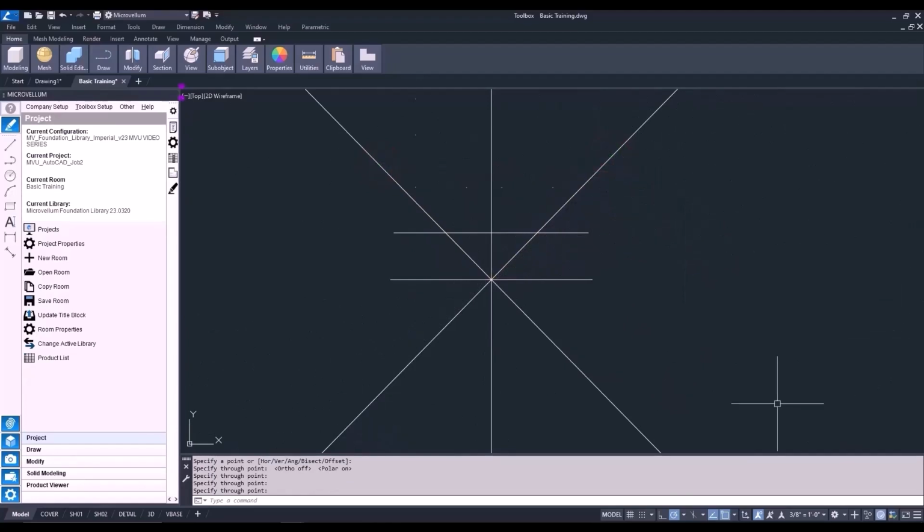Okay, so now back to the object snap settings. You go to the status bar again. Here you have the option to turn on or off that object snap. You can see in that help text, F3 is the shortcut for that. Next to that is a drop-down menu, and this is a preview of all the current snap modes that you have on. Select Object Snap Settings.